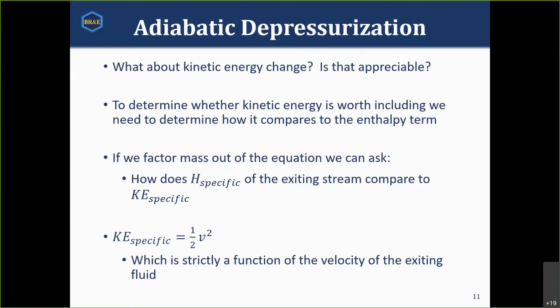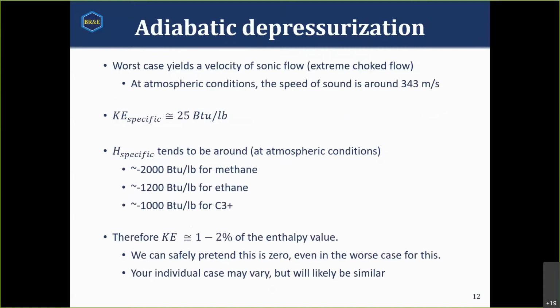And so when we look at our specific kinetic energy, it's 1/2 v squared, which is going to be strictly a function of the velocity of the exiting fluid. So what is the velocity of my exiting stream? Let's look at the worst case. Because if in the worst case the kinetic energy is small compared to enthalpy, I can ignore it in non-worst cases. The worst case would be a sonic flow, where you have sonic fluid leaving through your valve, leaving through your system, extreme choked flow.